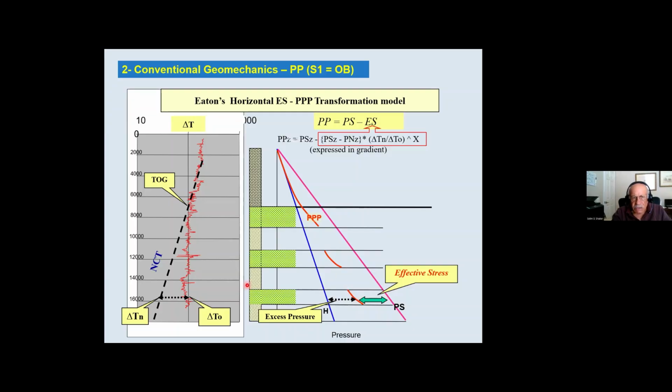We cannot use that model, the Eaton model, in the sand. I've been preaching that 100 times. You cannot use the effective stress and Eaton equation in the sand. In the sand, or the reservoir, the pressure is measured. You cannot predict it. This applies only in the low permeable formations, because we take this envelope here, that triangle, and we're going to move it here.